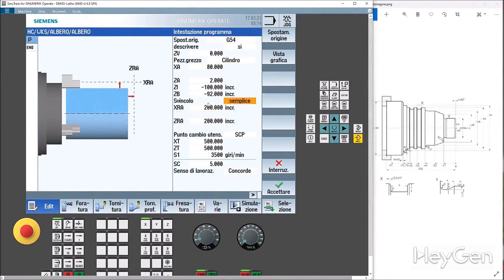Positioning the mouse over a box gives an indicator. I leave 200 mm of release in both X and Z, meaning I will move away to release by 200 mm incrementally in both X and Z. I can modify this later if I see that I'm moving too far away, but for now, while I'm setting up the initial program, I can proceed without worry.